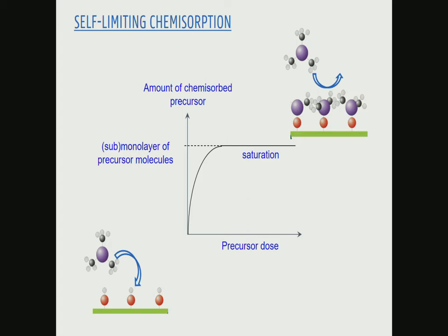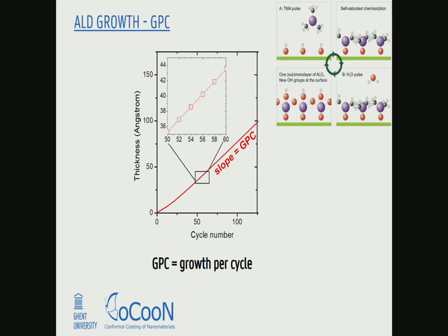So in the most naive picture, every time you're consuming all of your adsorption sites, but in reality, it's usually only a fraction, or not everything is accessible. And so atomic layer deposition should maybe have been called atomic sublayer or submonolayer deposition. The idea is there, but you should keep in mind that it's definitely not always a full monolayer that's being deposited.